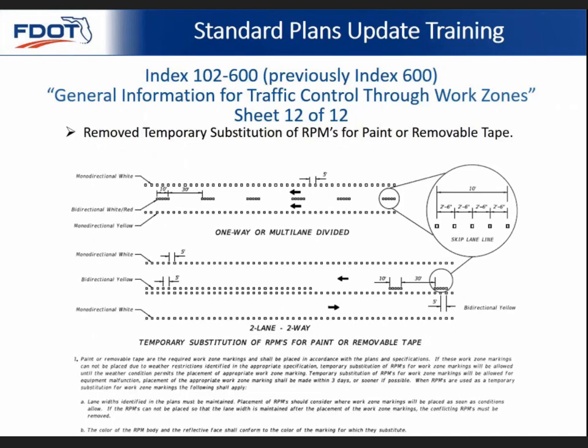That's because, according to the MUTCD, there was supposed to be an engineering study involved in the placement of this. It's typically not supposed to be used on the outside lane lines. So we don't really want this to be a frontline option, and we're not saying that it's not allowed, but it needs more thought if it's going to be used.